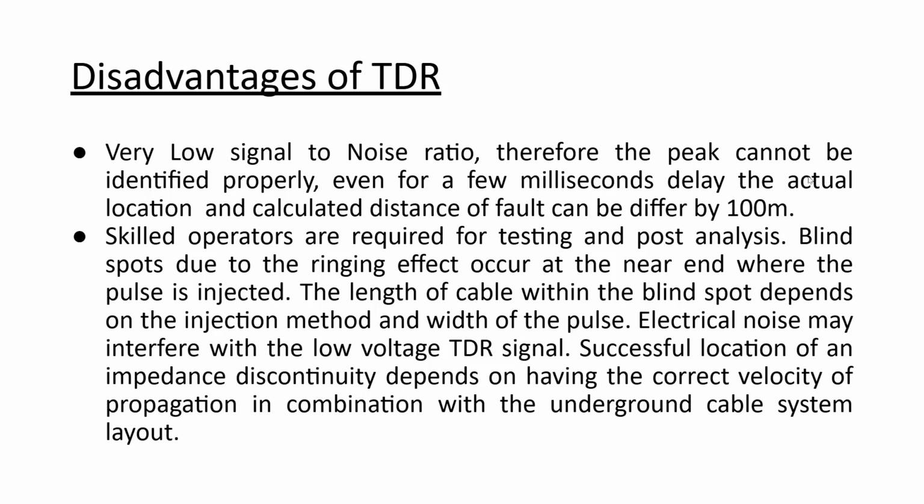Of course, TDR along with additional methods is used to pinpoint the location. So TDR is a basic method. It will give the approximate location. After that, there are several ways. For example, a hearing aid which can give us a buzz sound when the actual fault is located. So such kind of techniques are there.